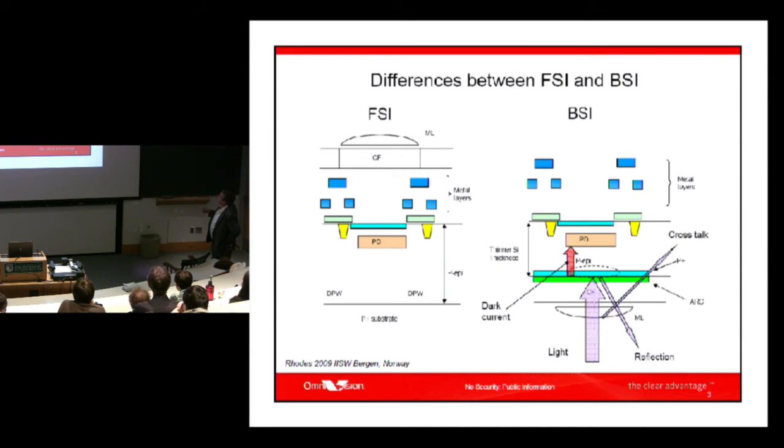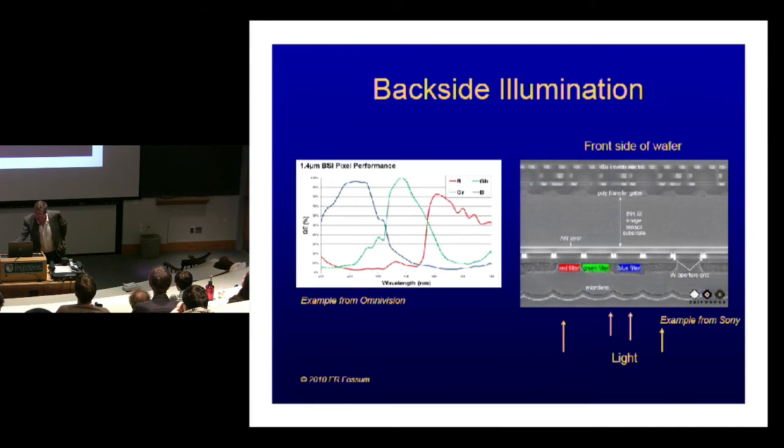In a backside illumination process, we start with this basic wafer. Here's the substrate of the silicon. The back of the wafer is normally way down at the floor. We grind that wafer away till it's quite thin, and now the light can come in from the backside and shine into the photodetector part, and we can put a microlens and color filter array on this side instead. That way we don't have to worry about these wires blocking the light from getting into the photodiode. So it gives us more freedom on the wiring or circuits that go up here if the light comes in from the backside. But this is an extra processing step, so it costs more. Still, that seems to be the trend.